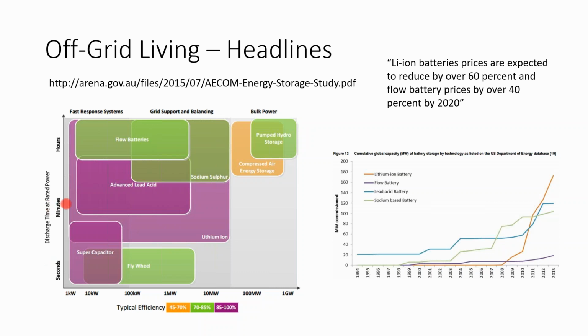And so, lead acid, being able to completely discharge a lead acid battery, you need a process that takes minutes rather than seconds. And even with lithium ion, you might have the ability to do a 60-second discharge, but still with, say, an elevator, maybe 60 seconds is not quick enough.